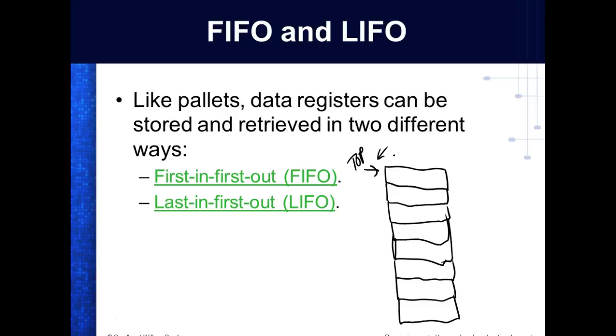This is our S2 register. One of the S2, it's S2:24. So the S2 register has a lot of stuff in it. That's where our counting registers are. I think that's where they keep, with a PLC that supports a real-time clock, I think it's up in your S2 registers. The index register is up in your S2 registers. So there's a lot of stuff in your S2 registers. So I think S2:4, is that the clock for you? So the index register is what? Yeah, it's S2:24.